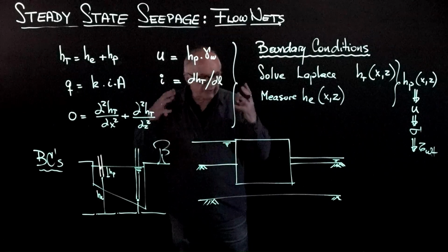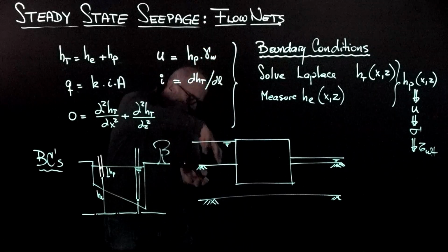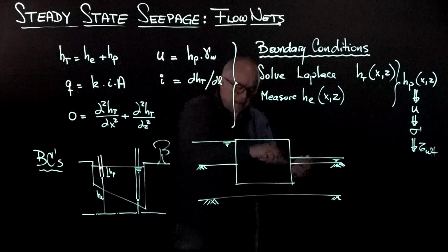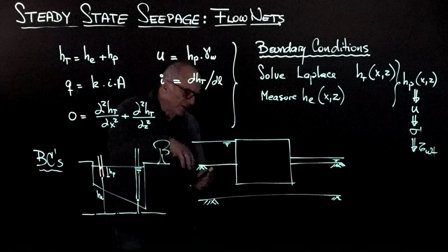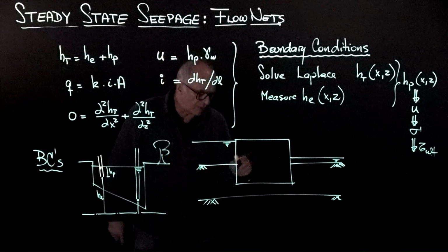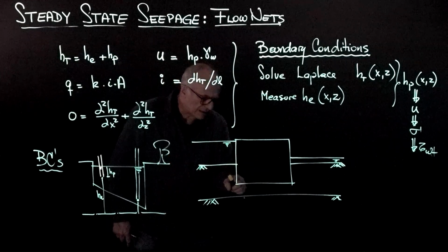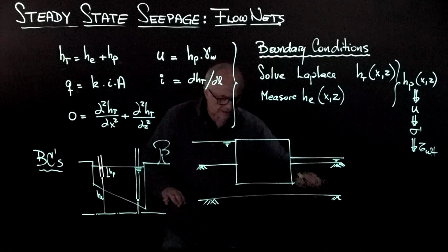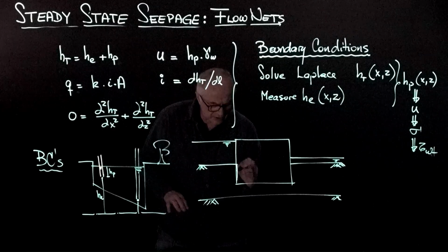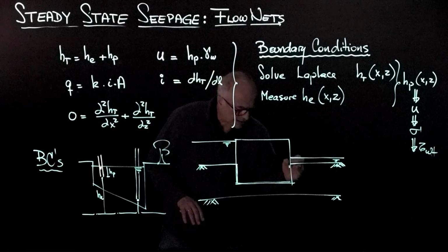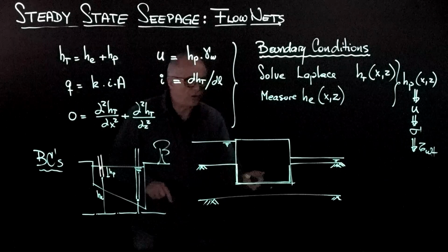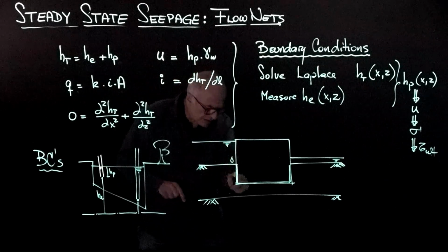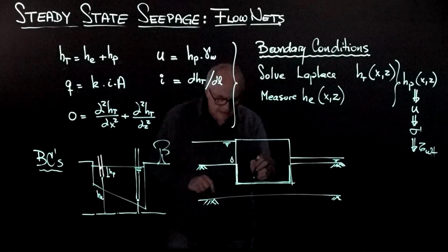We have to realize that water will flow through the subsurface as through a pipe. And so the water is channeled between this concrete block, this is one boundary for the flow, and the bottom aquitard. So this wall here is the shortest flow line for any water droplet to go through. That would be the shortest flow line.